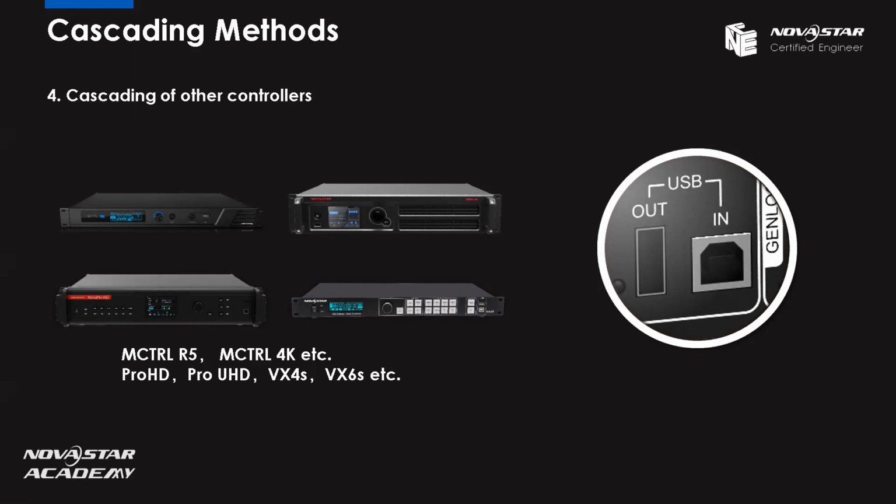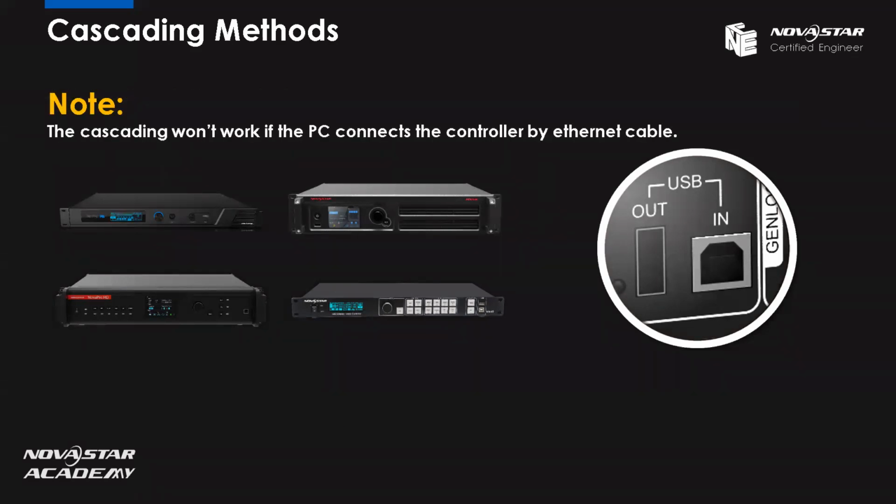Okay, but there is a note you need to pay attention to. The cascading won't work if the PC connects to the controller by the Ethernet cable. For these controllers, we support not only the USB cable to control, but also the Ethernet cable. So considering the distance, in some situations you may choose an Ethernet cable to connect your PC and the controller rather than the USB cable.